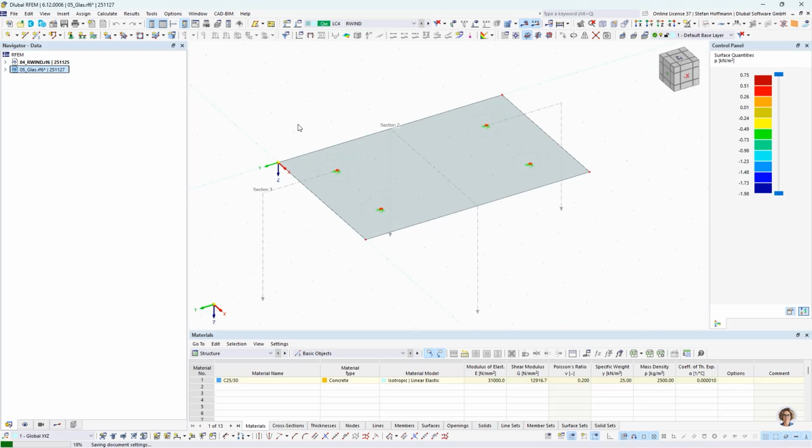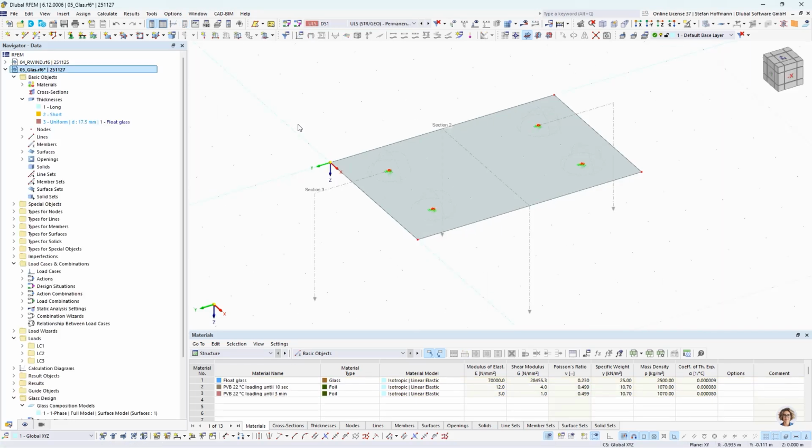The next question is, can I control the shear coupling for laminated glass in RFEM 6? So usually, of course, having laminated glass, the shear coupling is quite of interest, because if you have a layered plane where you have two panels of glass and one foil in the middle, then one worst case is that you do not take the shear coupling into account, having big deformations, having stresses only in the glass planes. But it might also be of interest, that is why we use laminated glass, that you can take into consideration the shear coupling. Sometimes you are allowed to do this.